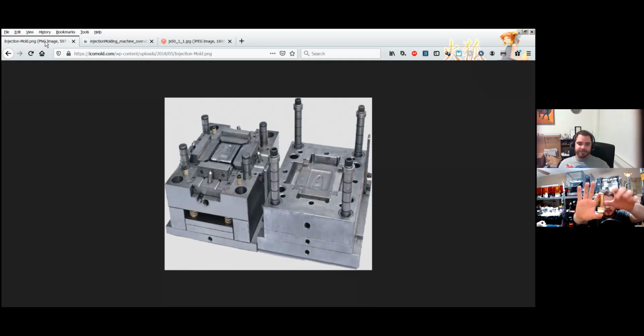We have a heat sink, which is a cylinder with a bunch of slits cut in it, so it's lots of surface area. You have a metal heat break, which goes between the heat block, which is a big chunk of aluminum or copper, and the heat sink. The idea is you want to transfer as little heat as possible, but you still need to have mechanical connection. On the bottom side of the heat block is the nozzle.